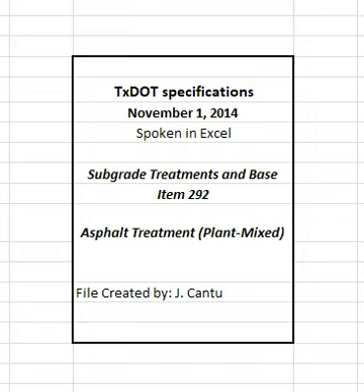4.4.2 Tack coat. Clean the surface before placing the tack coat. Unless otherwise approved, apply tack coat uniformly at a rate between 0.04 and 0.10 gallons of residual asphalt per square yard of surface area. Apply a thin, uniform tack coat to all contact surfaces of curbs, structures, and joints. Prevent splattering of tack coat when placed adjacent to curbs, gutters, and structures.